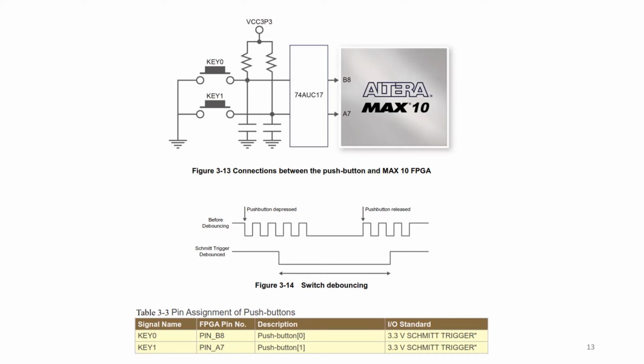Will it be low or high? High. Oh, okay, because it doesn't have a path to ground. So yeah, it'll be high. Yes, it will be high because it has the power here, VCC, going through the resistor to the input. Okay. When I hit this, it will be connected to ground, so it will be 0.